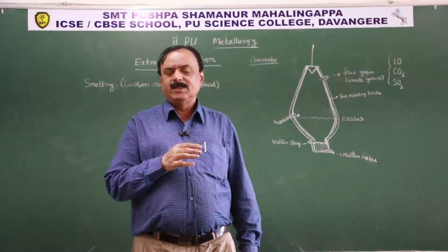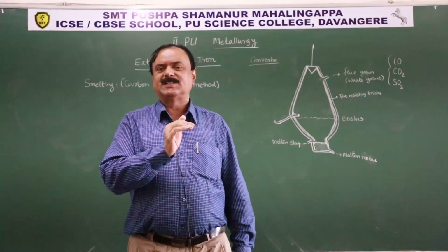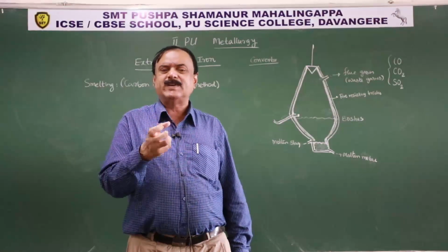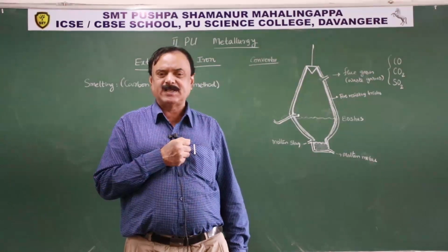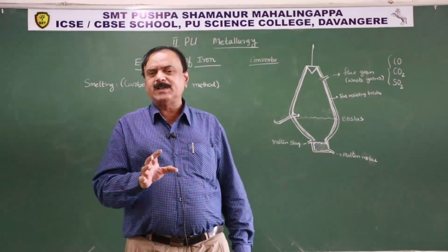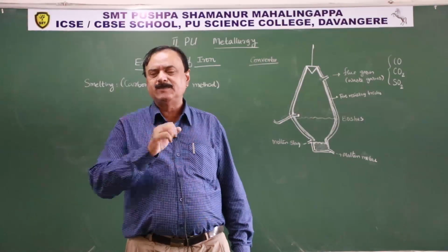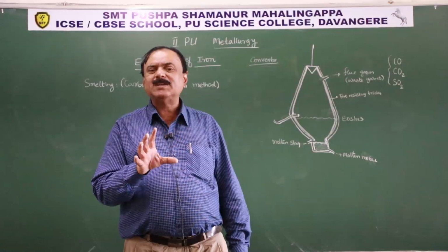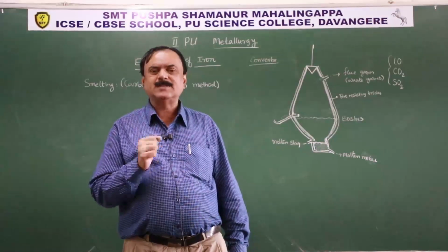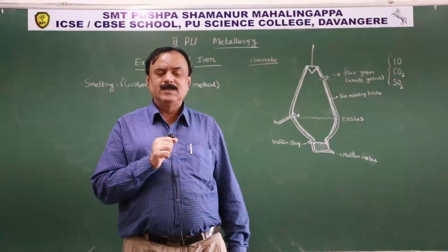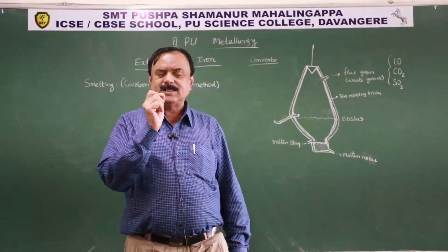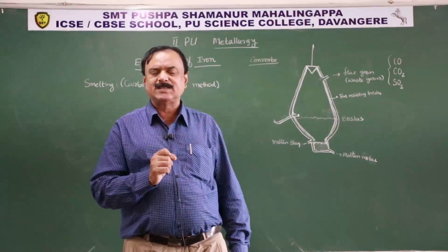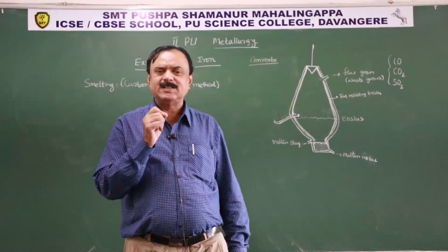Therefore, without protection, if such materials are directly used in furnaces for combustion chemical reactions, which provide a large amount of energy, at this high temperature there is a possibility of distortion of the material. That is the reason why it is covered inside by fire resisting or temperature resisting bricks.